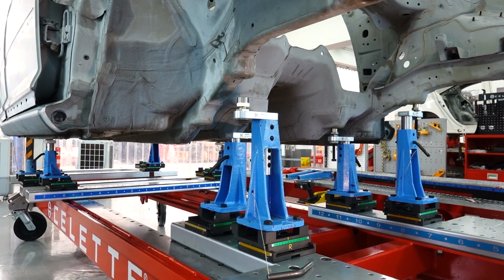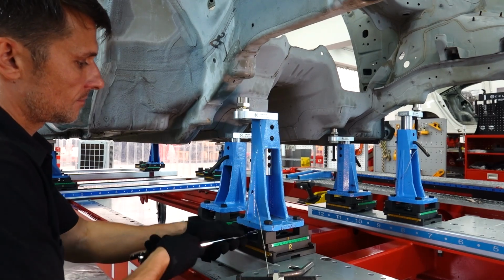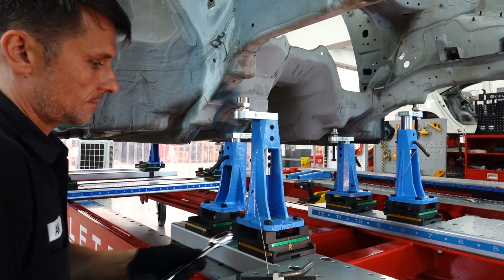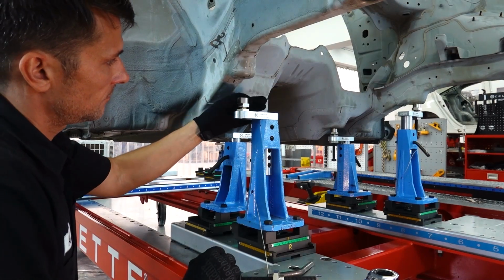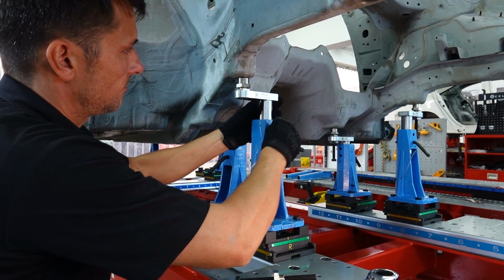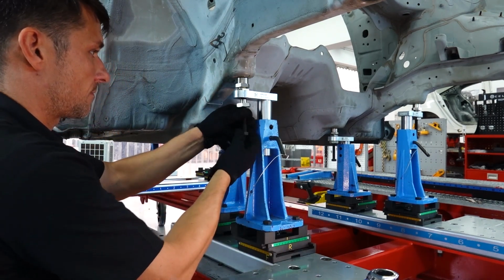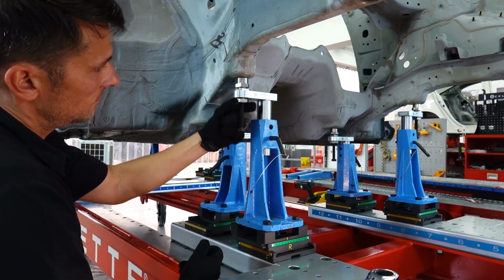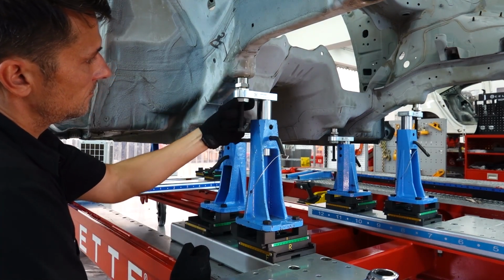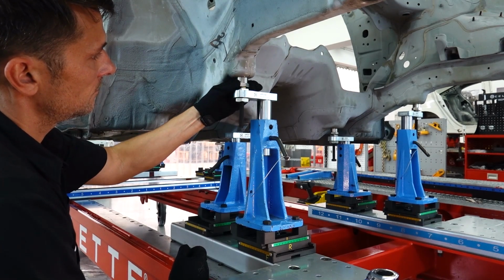First, we need to adjust the jig until the screw fits in the hole in the damaged position. In order to do this, we need to untighten the sliding block and lower the height adapter. We can now slide up the piston and secure it with the pin without hitting the car body. Adjust the sliding block, put the screw in, and screw the socket back up until it's tight against the car body.